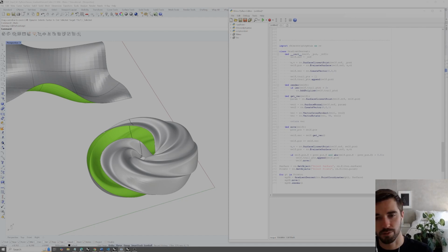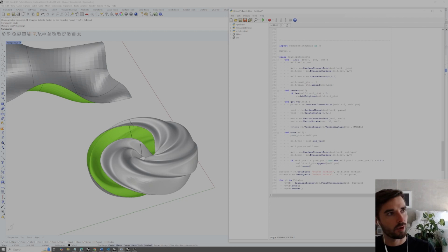So how do we control the vector value? We control the vector value where we're returning it here. So the first thing we might want to do is ensure that this is a vector with length 1. How do we do that? We unitize it. So this just takes that vector and basically scales it to a length of 1. Now what can we do? Now that we know that this is a length of 1 and consistent every single time, we can scale it by a parameter maxVal.